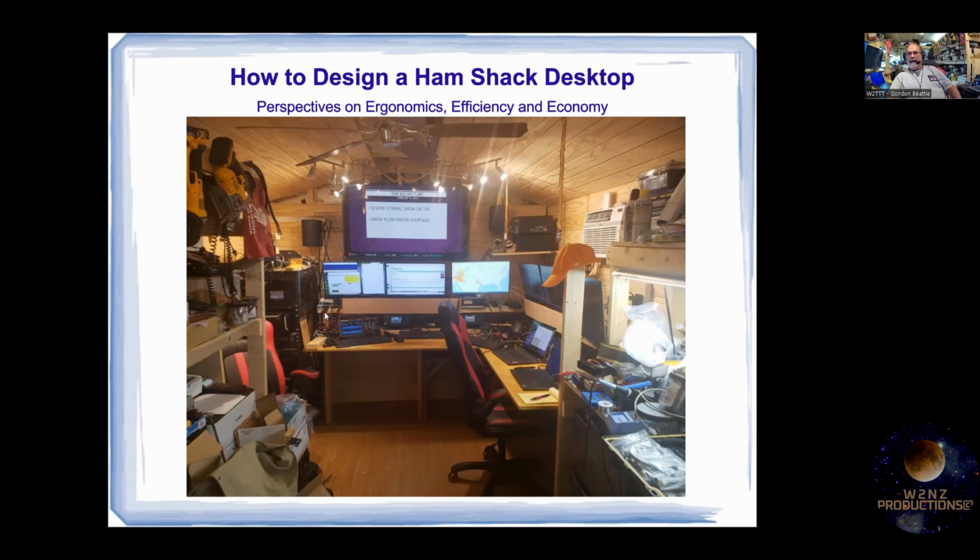And then it feeds a connector that you can't see over here, a big 75 amp Anderson Powerpole, the kind you use to charge a vehicle. And then it goes directly to Rig Runners that are, again, hidden behind, that you can't see. I bought the 80 amp Rig Runners. I bought 2 of them and it's not enough. So I have to put a third one in here at some point. And that's that.